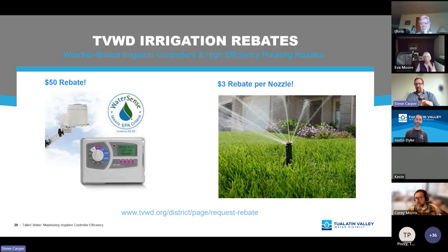So again, it's not a terribly technical fix, but it can be a little tricky, because you have to dig down just enough so that you can create some clearance underneath the sprinkler to push it down or raise it up, whichever the case may be. It sounds like in your case, it might be set a little bit too high for a lawn setting, but it depends. You want to evaluate that. If you clear away the turf from the head, you want to be able to, again, see the entire top of the sprinkler.